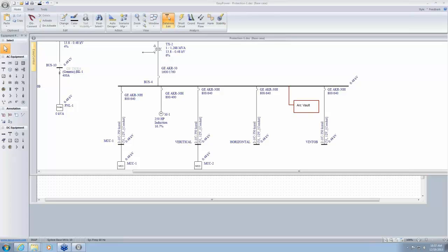In a lot of cases, just to simplify the process, people have avoided having multiple labels on the same switchgear or switchboard, and they just stick with the worst case hazard, whatever may be the incoming hazard, or using the excluding main condition. That simplifies the approach. Of course, you might be getting higher hazards based on that calculation, but it may also avoid confusion that is created by multiple labels on the same equipment.